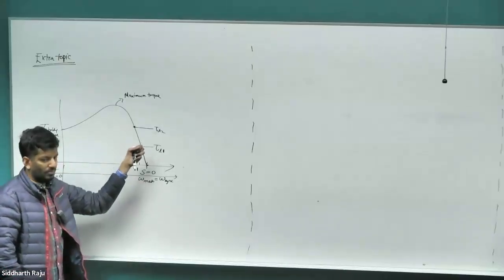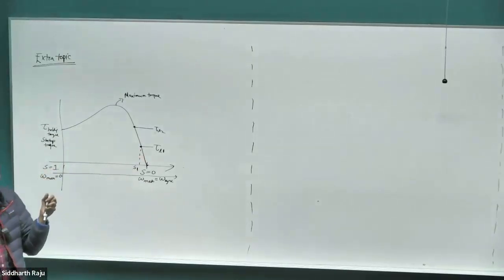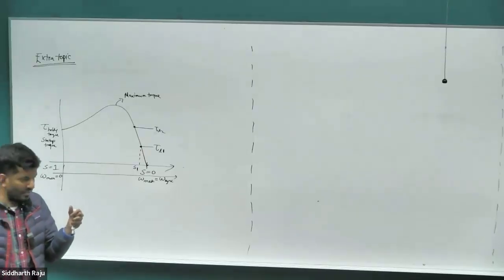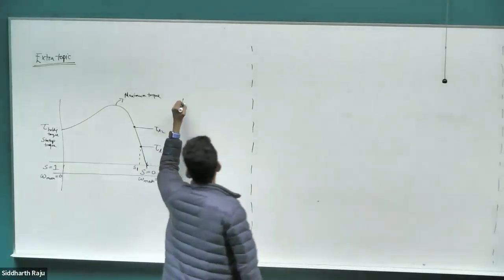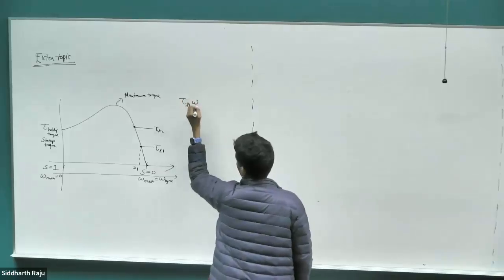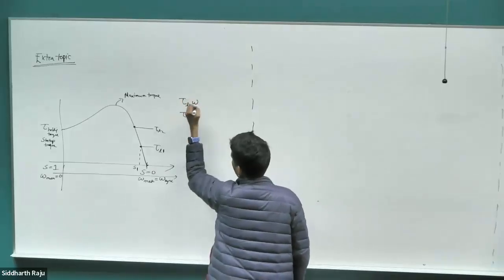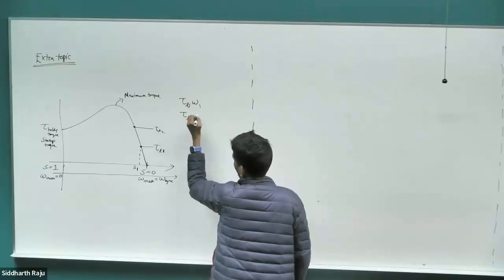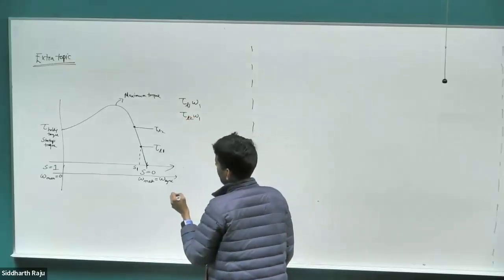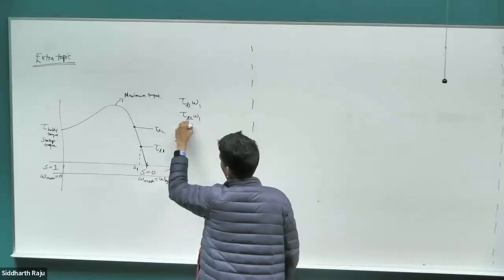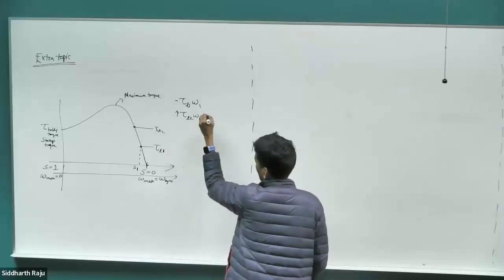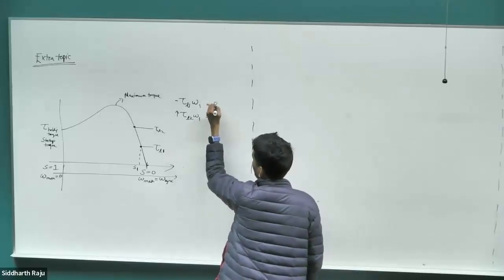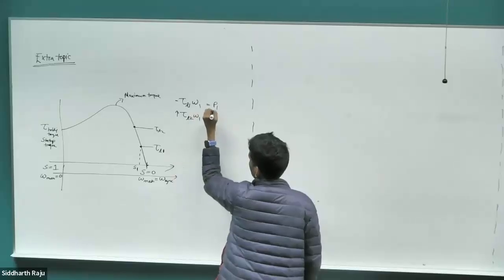As soon as the load torque doubles, the electromagnetic torque is not going to double. We have seen this already happen in a permanent magnet synchronous motor. What happens? The rotor starts to slow down. Previously, the motor was supplying tau L1 times omega 1. Now the load torque has suddenly increased, but the speed is still at the same point. So it's going to start to draw more energy, so this is drawing more power. So P2 is greater than P1.